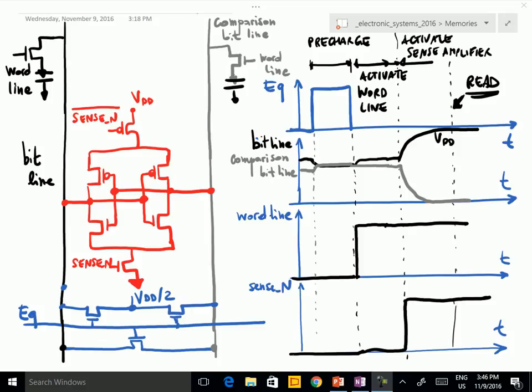And for this reason, independently of the read operations that are necessary, there is always a process going on in DRAMs of so-called refreshing the memory. The process is called refresh. Basically, there's a finite state machine which in turn addresses all the memory cells, and reads the information in each memory cell. It does this because when the information is read, there is a restore. The sense amplifier starts, and the voltage level on the capacitor is completely restored.